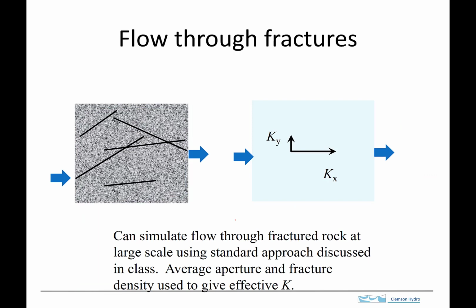So the first thing that it would do is lead to the conclusion that we could represent fractured systems, at least the large scale flux through a fractured system, using Darcy's law and using an equivalent hydraulic conductivity.